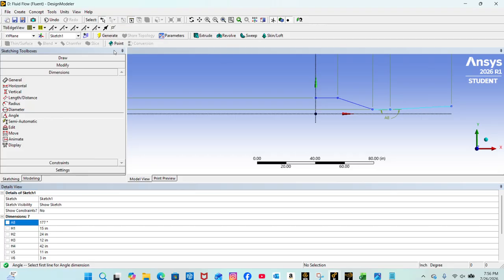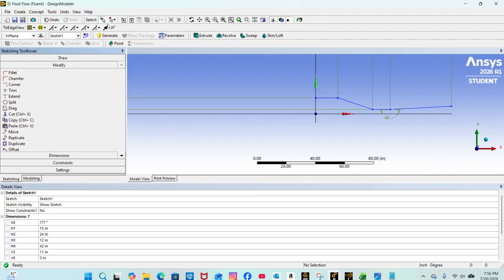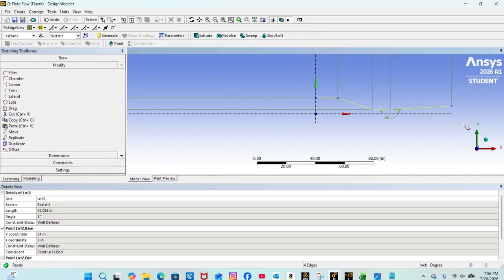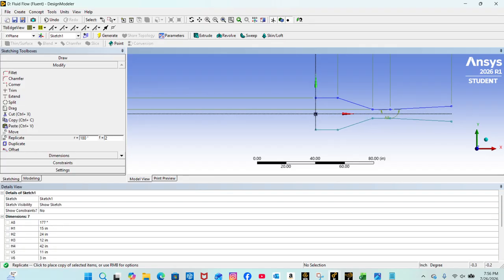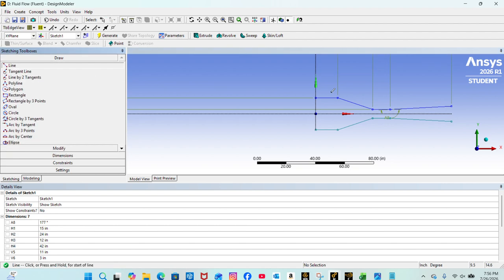Alright, here is the important part. Normally this gets complicated sometimes. Go to box select, grab it, then we can go to replicate, do 180. And before you even place it, tap it in the center. Because if you tap it in the center, when you do the flip horizontal and you double tap it, it'll do it perfectly for you. That is the easiest way to do it.